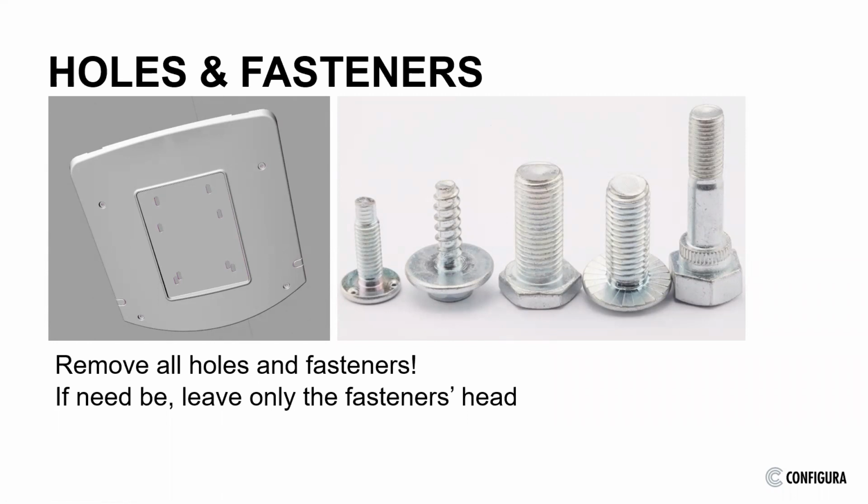So sometimes, yes, these elements are part of the product and design itself, and sometimes the holes matter as well. Say, for example, the holes for pallet racking uprights, those are actually mounting holes that are important to showcase, but you might want to simplify them into just a square hole instead of a round one. A round one always adds so much more polygons than a square one.